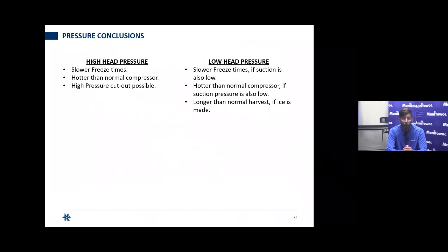You're going to have a hotter than normal compressor. Discharge line's going to get hot. Top of that compressor could get hot. Depending on how bad things are going, whether it's a pressure regulating device like a fan cycle switch or water reg valve, you could have a high pressure cutout. At that point, you're going to want to go diagnose what's controlling head pressure.